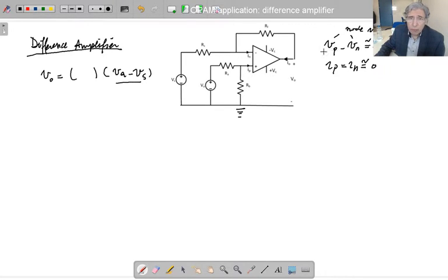And this Vp is the voltage between this node and the ground, which is also the same as the voltage of Rb. So, node voltage, that's why we gave an explanation. But the difference between those two voltages gives me the voltage between these two terminals. It says here this is equal to 0. That means this is almost short circuited. Voltage is 0, it means short circuit.